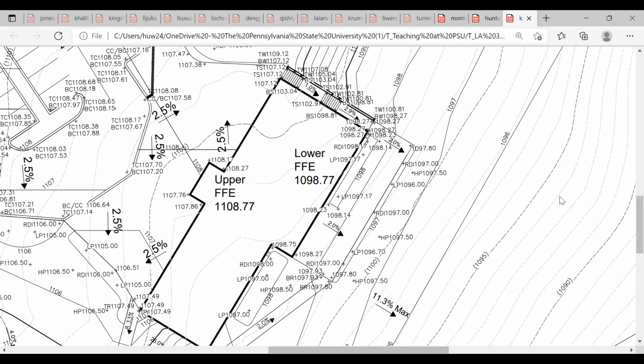If the building roof water is not very dirty, and it is not necessary for the planter to serve a water quality function, it reduces the peak, of course. It detains the water and slowly releases it to the next system, but the benefit doesn't outweigh the cost. So this could be a nice conveying system, but I definitely would not expect it to perform infiltration.